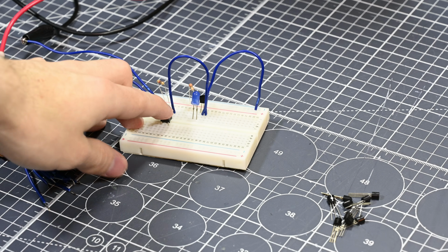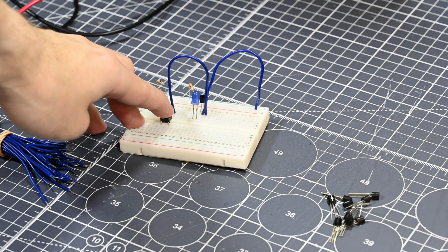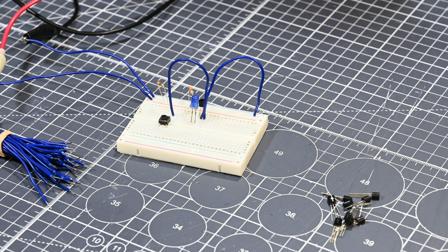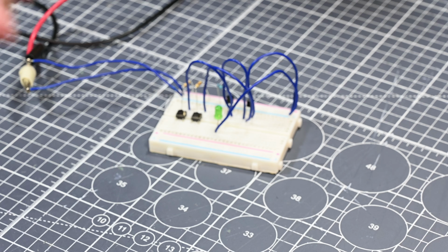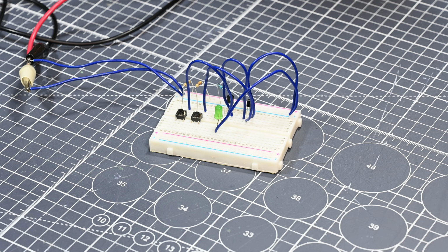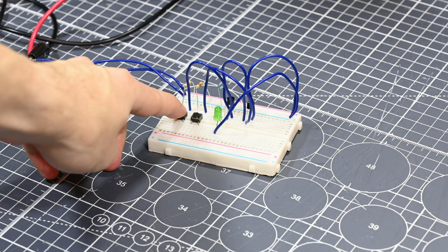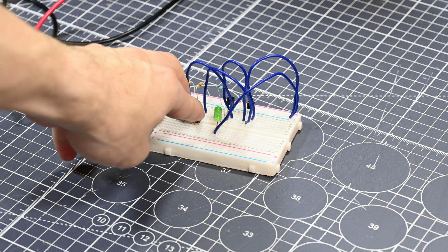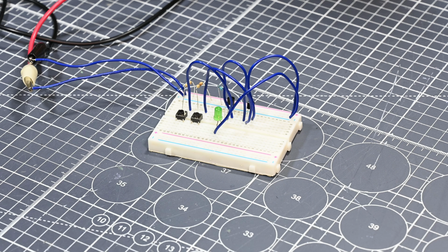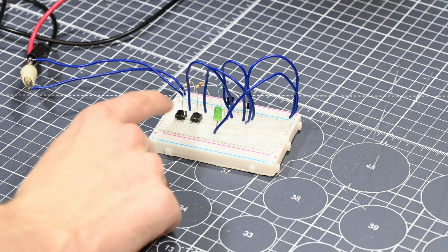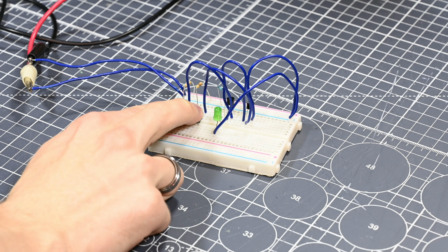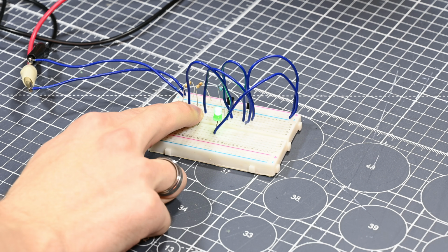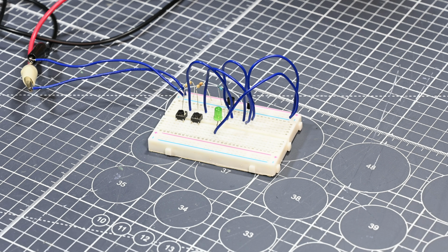When transistors do get special though, is when multiple of them are combined in different combinations to form what are known as logic gates. For example, I built up this small circuit here with 2 transistors and 2 buttons, which forms an AND gate. This gate takes the 2 inputs from the 2 buttons and only turns the LED on when both of the inputs are also on. So, if one input is on and one is off, the LED is off too. And if both of the buttons are off, then the LED is still off.